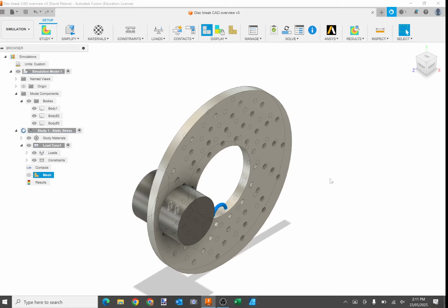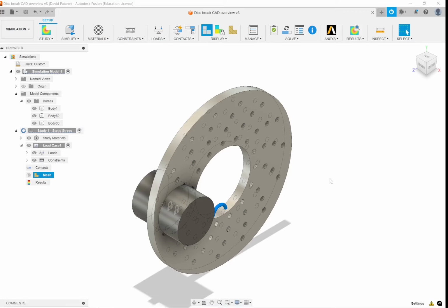It's not loading up. But a mesh is where we're assuming this is heaps of little tiny triangles, and it's basically like one big truss analysis, one big stress calculation, one big simultaneous equation to see what would be the amount of force going through each individual element of this disc brake. The actual name for that is FEA, standing for Finite Element Analysis. So we're choosing how many times you want to simulate this object.